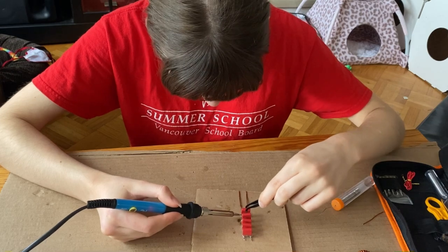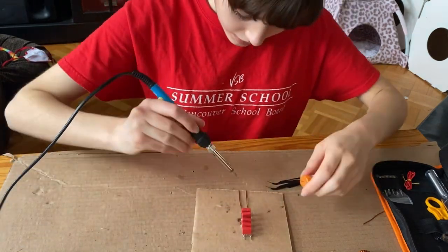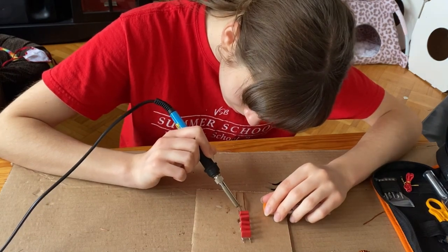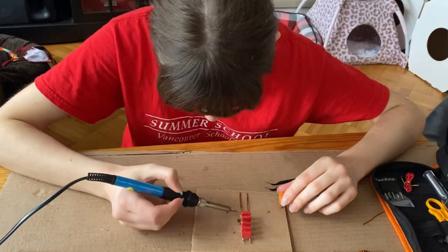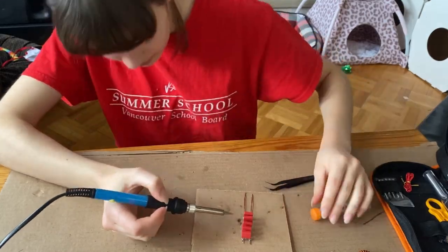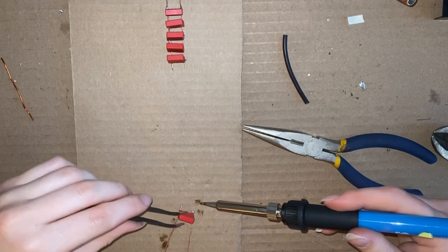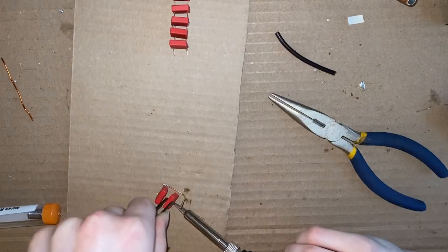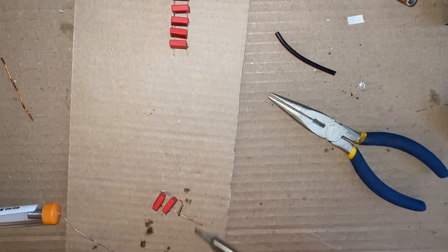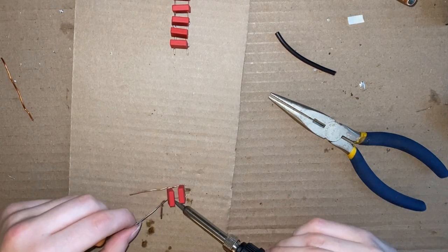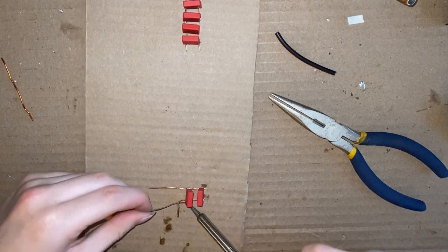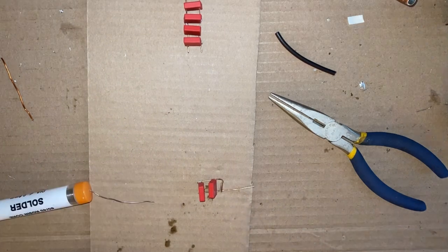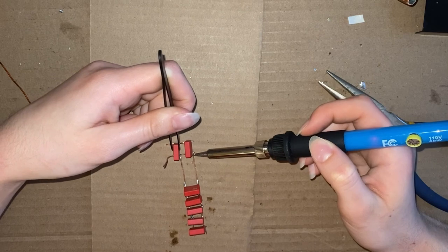The reason why I soldered 5 capacitors in parallel instead of just using one capacitor was so that there's more surface area available for power dissipation, which is in the form of heat. Also, soldering multiple capacitors in parallel reduces the total effective series resistance. Since higher resistance means more power dissipated, a lower effective series resistance will reduce losses due to power dissipation. These capacitors that are connected in parallel are called capacitor banks.